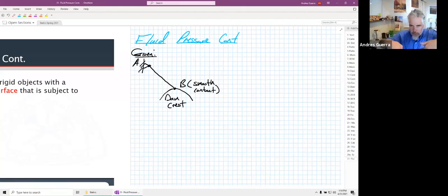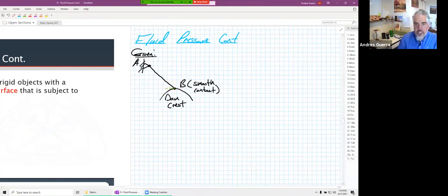Concrete is really good in compression, and so that pressure going down into the dam is actually going to stabilize the dam. And so we were shooting for an angle of 45 degrees. Because of the geometry at the top of the dam there, we got actually closer to 42 or 43, if I remember correctly. Let's just put, for our example, let's make this 40 degrees. So we're going to have a 40-degree angle right there.